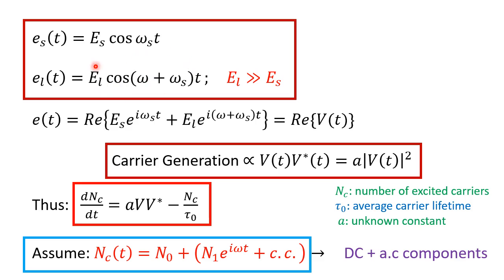So you have essentially a frequency shifted local oscillator, which is stable. It doesn't drift, both in phase as well as in amplitude, and the amplitude of the local oscillator is much larger than the signal amplitude. So now if you look at the total field, total signal at the detector, we are looking again at the complex notation.